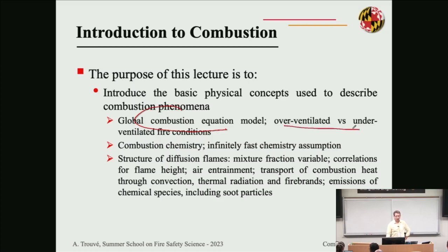This is good enough also to differentiate between over-ventilated and under-ventilated fire conditions, which is an important aspect of fire systems. The combustion chemistry, I will mention in passing to lead to the conclusion that we don't really need it. Of course, there are exceptions to this statement, but when a flame is established, typically the flame chemistry is, quote-unquote, infinitely fast. Infinitely means much faster than other mechanisms at play in combustion processes, in particular the transport of fuel and oxygen to the flame zone. And so you're going to be rate limited by the slowest process, so you can forget about chemistry. Chemistry, in our eyes, is going to be infinitely fast.